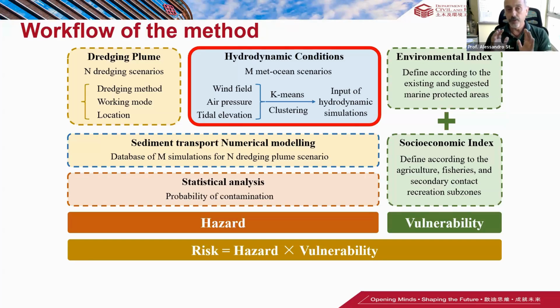The core of the approach is in these red blocks, where we rely on some very simple machine learning techniques to decide what are the typical meta-ocean scenarios. So what are the typical wind field, tidal elevation, air pressure in my site where I have to design the dredging operation. Then you go for the sediment transport numerical model. So at the very end, you will have, I will show you later, hundreds of scenarios analyzed. So the hazard that you are computing has a very high statistical significance.